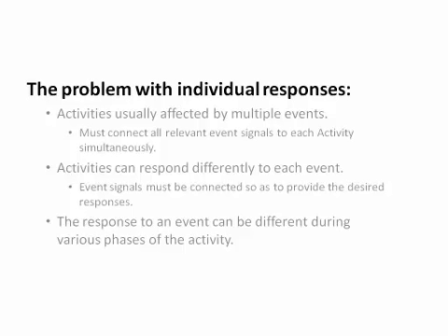So because we have different responses in different phases on the same equipment processing the same item, I typically divide my activities into phases. The phases are designed and divided according to what activity responses will be available and what resources are required. So in addition to considering what failure modes can happen during that phase, I also consider things like whether labor is required during that phase.